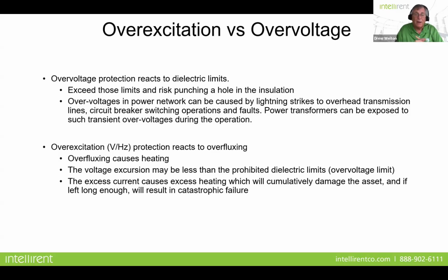Overexcitation protection reacts to overfluxing. So we're talking about overfluxing. Flux causes heating. The voltage excursion may be less than the prohibited dielectric limits or the overvoltage limit, but the excess current causes excess heating, which will cumulatively damage the asset.